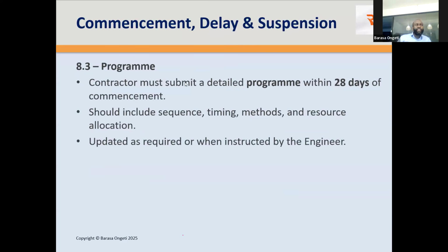8.3 says the contractor must submit a detailed program within 28 days of commencement. It should include sequence, timing, methods, and resource allocation. So if you read clause 8.3, it gives you these four things: sequence, timing, methods, and resource allocation. So that means your program should have those things. If you've ever prepared a program here, or if you've ever received a program from a contractor, those are the things that you need to look out for.